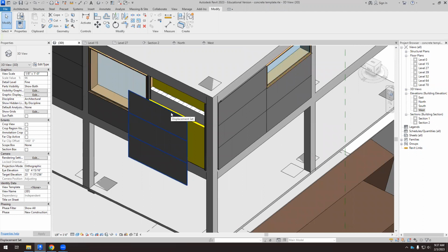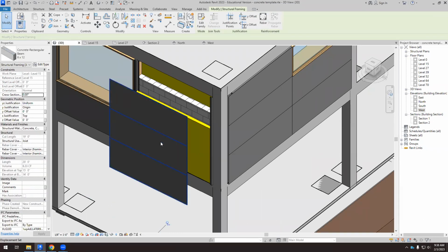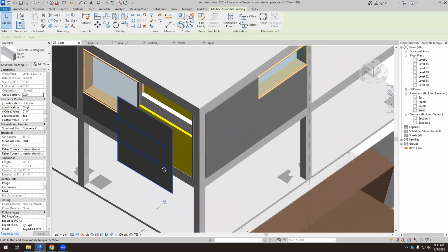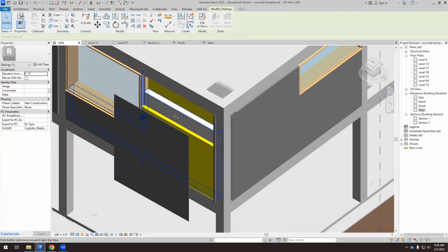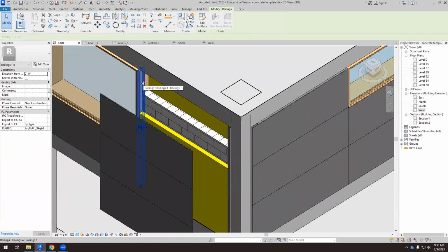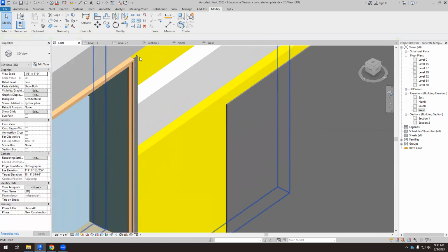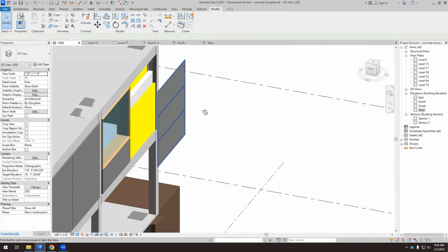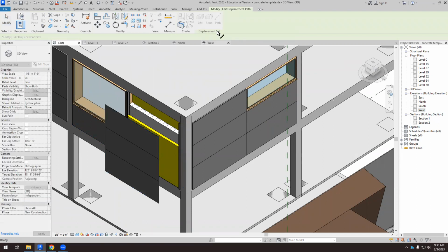So we have a wall, we have to create different layers, then we have to create parts. With parts, we can work with different layers by showing the shape handles, and then we can divide parts. So if you want different panels, you can divide these parts, and by using the extrusion or the model in place, we can have these elements in 3D. And well, from the construction, this is what we need, because things are not floating. And now if we add this, we can always use a path.